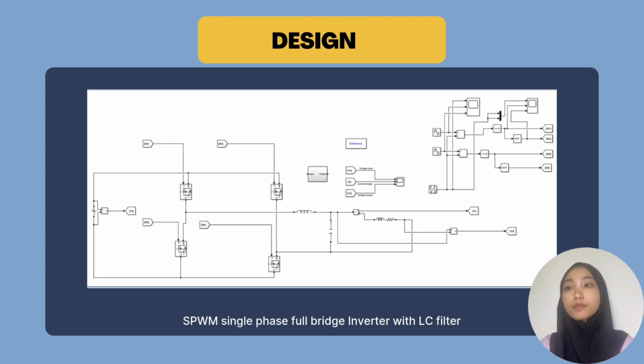So today I will present about the design. This is the SPWM single phase full bridge inverter with LC filter. The parameters set in the simulation are: VDC is 269 volts, the resistor is 14 ohm, the inductor is 0.3 millihenry, and the frequency for this system is 50 Hz.